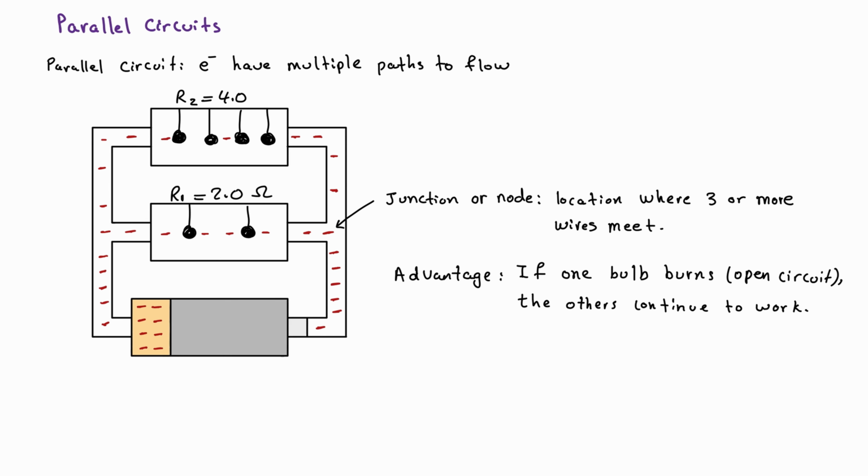these short circuits, it means that all the current will start going through that path because there's no resistance there. So there's some resistance here, no resistance here. So when the electrons are being pushed and there's resistance here but no resistance here, all of them will end up moving here. The speed of those electrons will increase, current increases, heats up, and it could damage the different parts of the circuit. That's why typically we use different components in order to help avoid that.